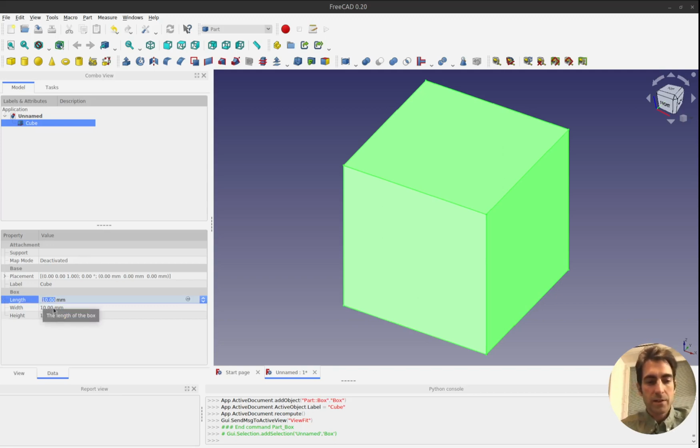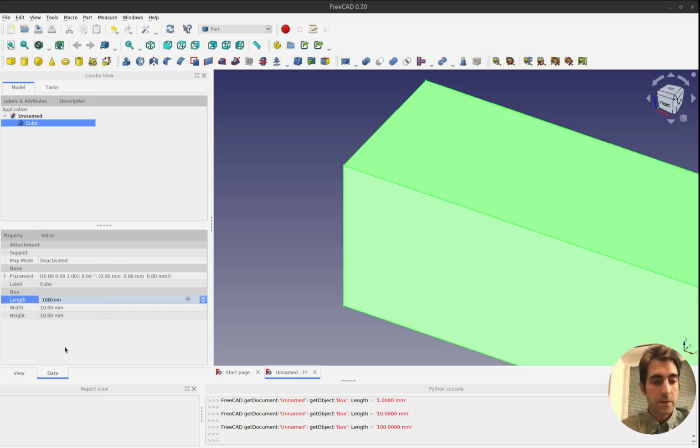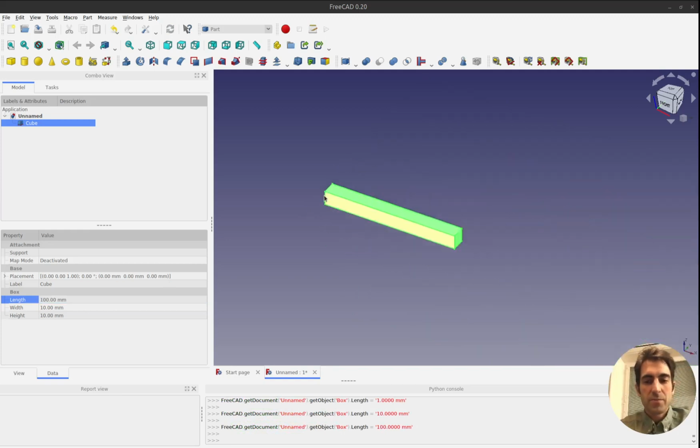By the way, have a look at the unit. We have it here in millimeters, so that's important. I'm going to put like 100. It's a thick beam. It's not a real Bernoulli beam that you learn in mechanics of materials. This is more like a thick beam, so for this we cannot use beam theory. Even if I do simple bending, I cannot use beam theory because it's too thick. If I make it longer or more slender, then I can use beam theory. Other than that, I need to use a three-dimensional calculation, which I'm going to do here as well.